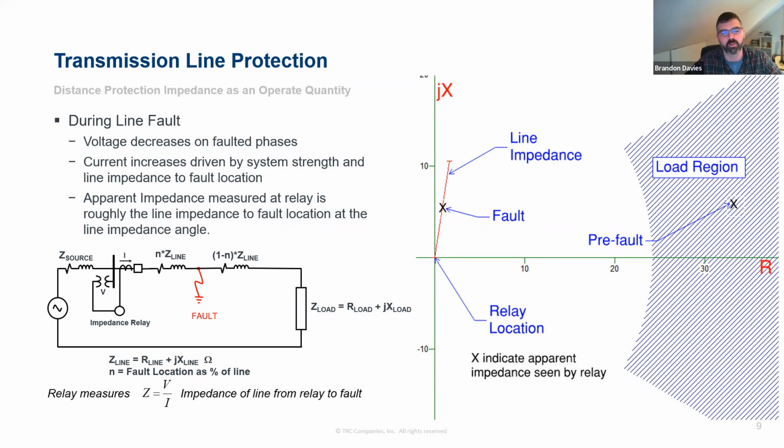And your really common transmission line fault modes don't have a large impedance or resistive component to change this. So when you look at actual fault results, you'll see a little bit of deviation, but generally you're not jumping way off to the right. Especially on multi-phase faults. A single line-to-ground fault might have a bit more impedance, but a multi-phase fault usually has a little less fault resistance, just because of how the fault happens electrically. But yeah, great question. Okay, thank you.